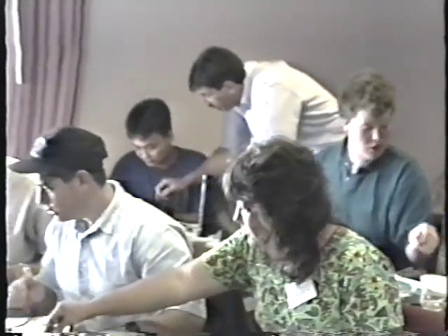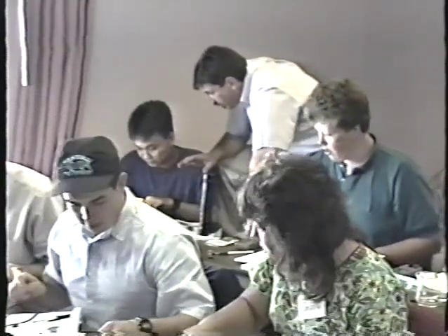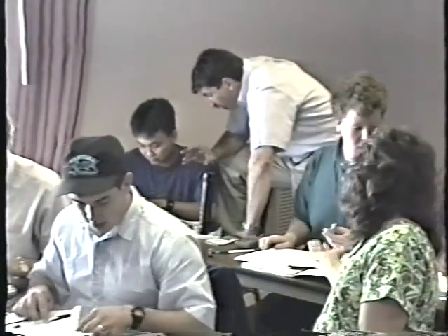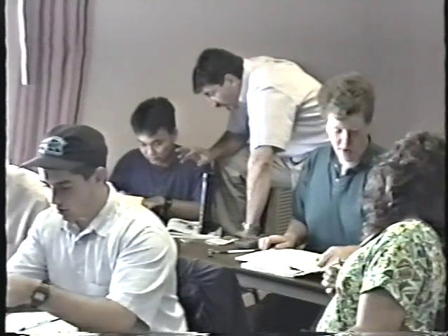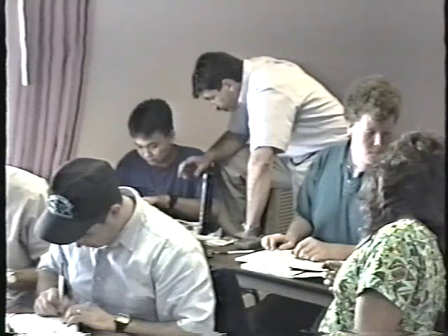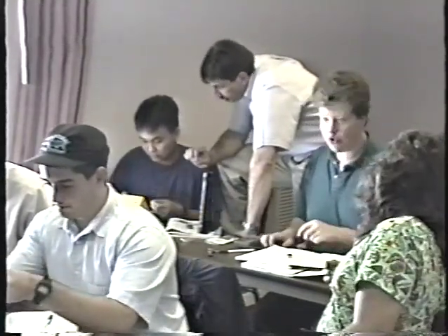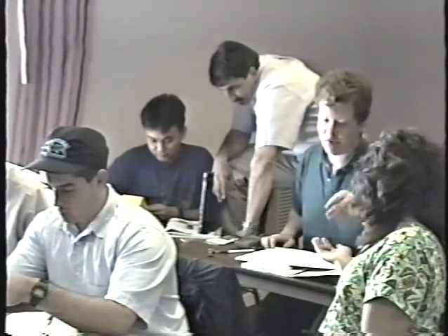Now, final check. Collector to emitter. Very important. The collector, which is the case, to the emitter. Doesn't matter which lead you put where. Should be open. Now reverse your leads. Same two pins. Are you done with 20? Collector to emitter. There you go. Open. That's a good one. You can go as fast as the other way.